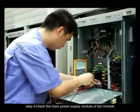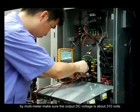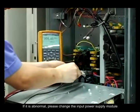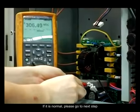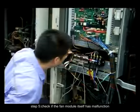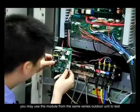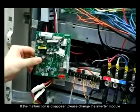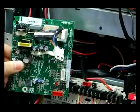If normal, please go to the next step. Step 4. Check the input power supply module of the fan module with a multimeter. Make sure the output DC voltage is about 310 volts. If it is abnormal, please change the input power supply module. If it is normal, please go to the next step. Step 5. Check if the fan module itself has a malfunction. You may use the module from the same series outdoor unit to test. If the malfunction disappears, please change the inverter module.